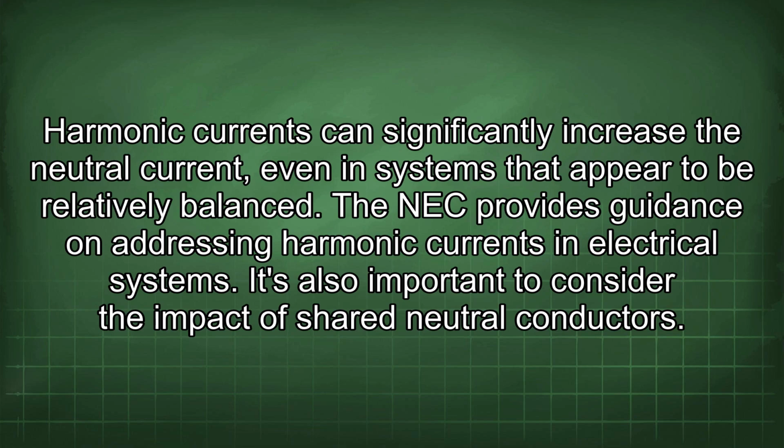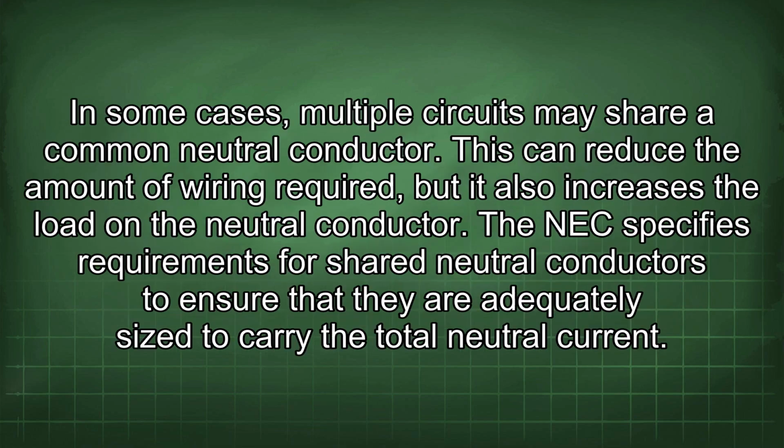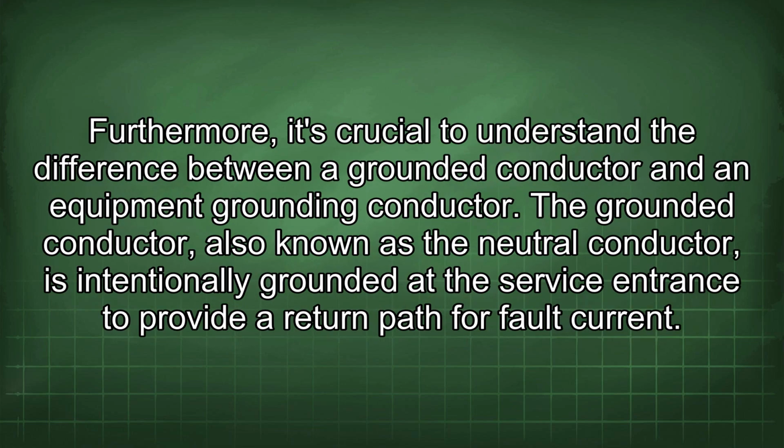It's also important to consider the impact of shared neutral conductors. In some cases, multiple circuits may share a common neutral conductor. This can reduce the amount of wiring required, but it also increases the load on the neutral conductor. The NEC specifies requirements for shared neutral conductors to ensure that they are adequately sized to carry the total neutral current. Furthermore, it's crucial to understand the difference between a grounded conductor and an equipment grounding conductor.